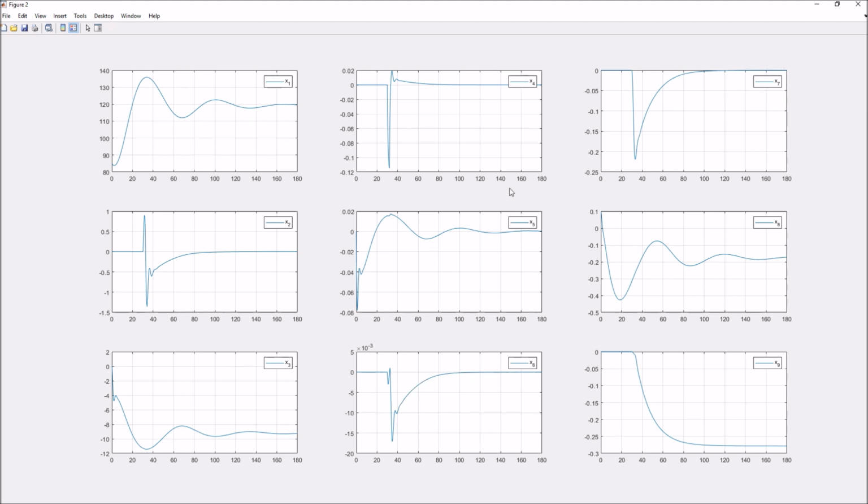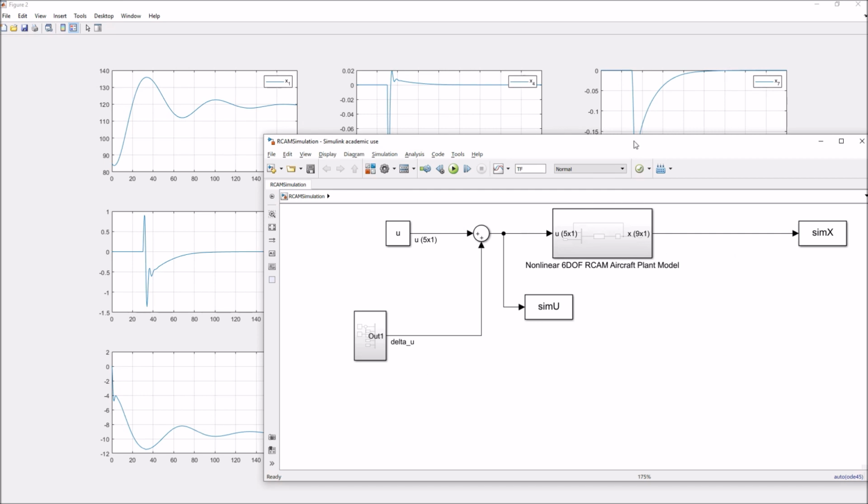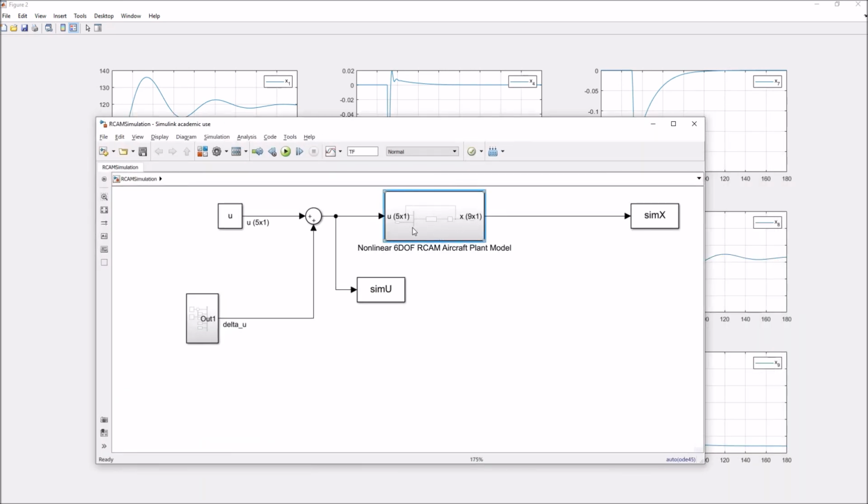And look at this. Luckily for us, it looks like even with this aileron kick, the system becomes stable and stabilizes out. However, look at this. It stabilizes, and now it's no longer heading due north, right? Psi has moved to almost -0.3 radians. So this is really interesting. There's a lot of interesting behavior now in this model that we're going to explore later. But long story short, at this point, we've set up a pretty good representation of an aircraft here in this block. So maybe what we should do right now is revisit that discussion of the limits and the saturation.